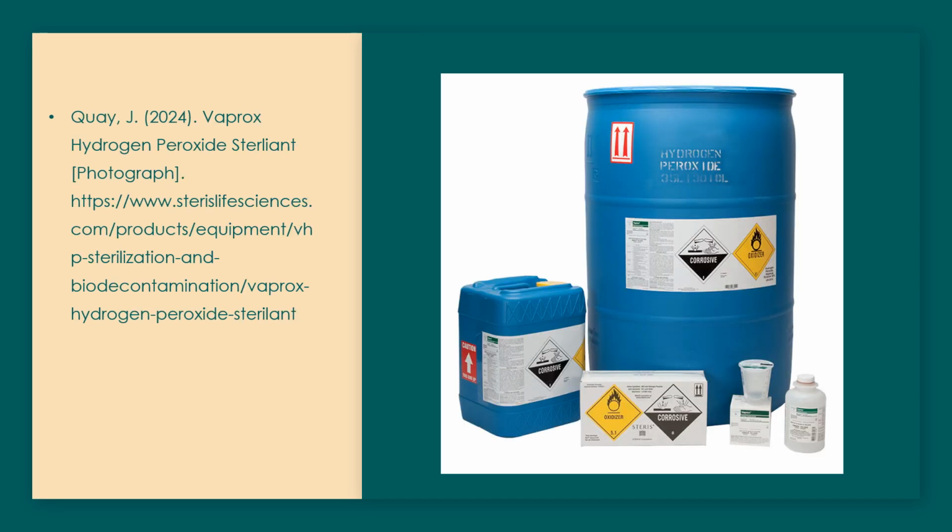Vaporized hydrogen peroxide is a low-temperature process. The temps will range from 82 to 104 degrees Fahrenheit. This happens in a deep vacuum process where the vapor falls in the chamber. The oxidizing agents kill the microorganisms, then the vapor is vacuumed out, leaving the products of water and oxygen, making this a very safe process.